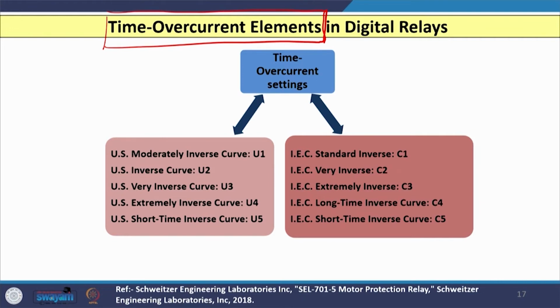Time overcurrent logic or elements are given in digital relays to achieve protection against short circuits. So, if any short circuit occurs, then that can be protected using time overcurrent elements. Here protection can be in terms of instantaneous or it can be in terms of time delayed. So, let us see how this can be done.